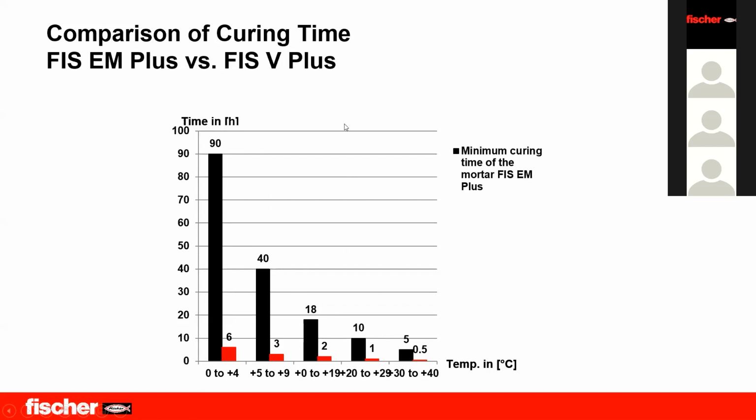So in some cases, if the project is fast moving, or if you want to finish your job, if the load is not that critical, yes, even vinyl ester is also a good option. I hope gelling and curing time is clear. If you have any questions, please don't hesitate to ask in the question and answer session. At the end of the session, we will answer all the questions.